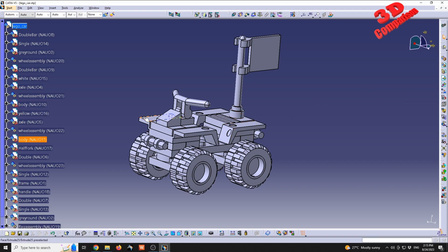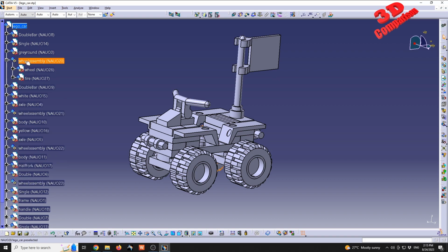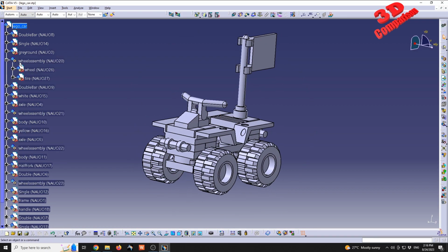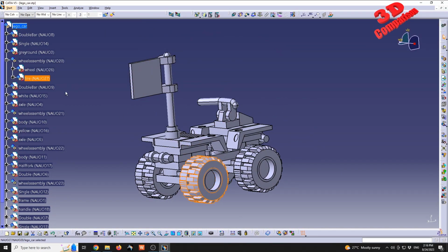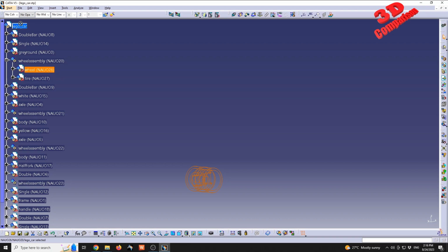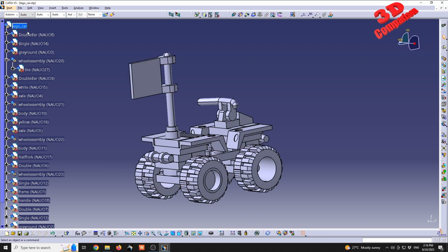Now, to get started with the assembly, we see that this Lego car has a main product, but there are also multiple sub-assemblies. For example, the wheels are like this, so we have a sub-assembly for the wheel. I'm going to change this, and go with all the components directly within the main component. If you expand the wheel assembly, we're going to see that it has a wheel part and a tire part. So these are those two elements, and I'm going to select those and drag and drop them onto the main product.